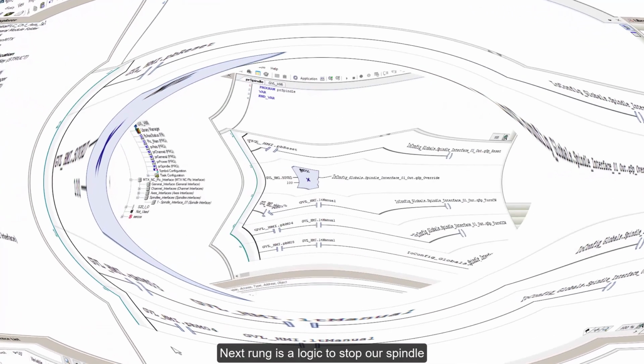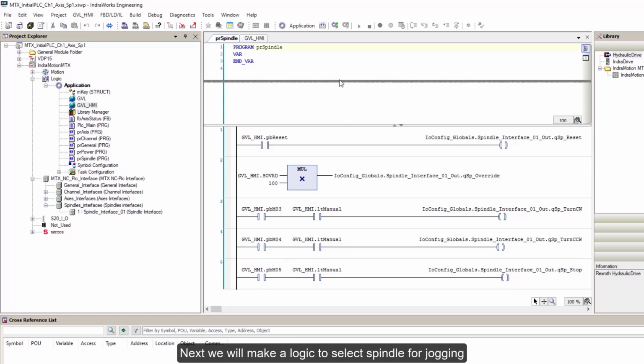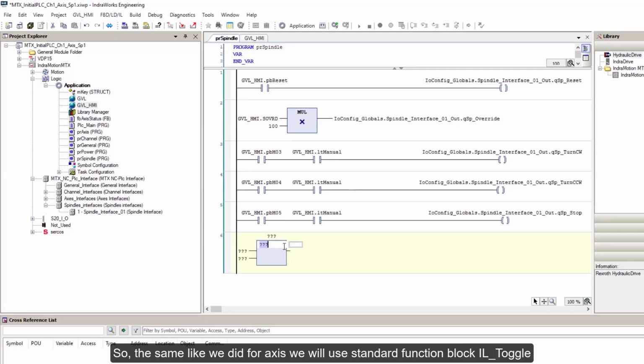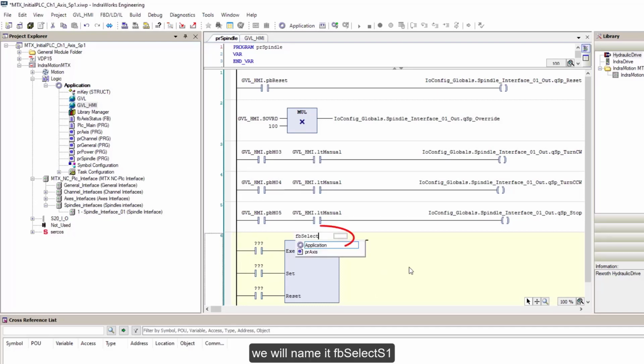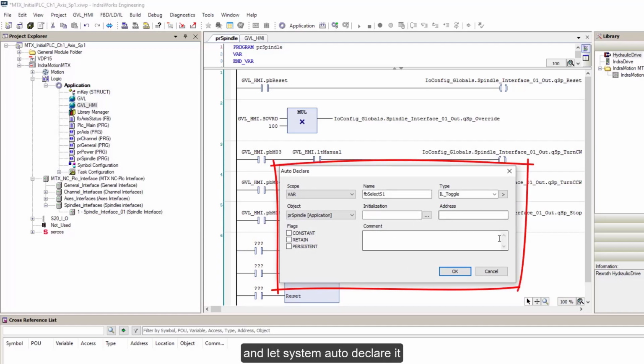Next rung is a logic to stop our spindle with output interface signal QSP stop and activated by push button PB M05. Next, we'll make a logic to select spindle for jogging. So, the same like we did for axis, we use standard function block IL toggle. We'll name it FB select S1 and let system auto-declare it.